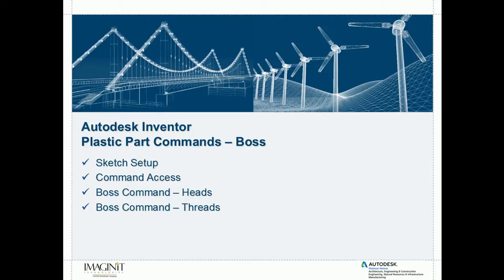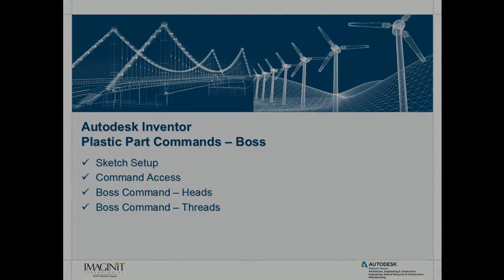In this Imagine It tech tip, we're going to take a look at the Autodesk Inventor plastic part command called the boss tool. We're going to talk about how to set up a good sketch for this, how to access the command, and also, when we're inside of the command, the two different types of bosses we can create, the heads and the threads.